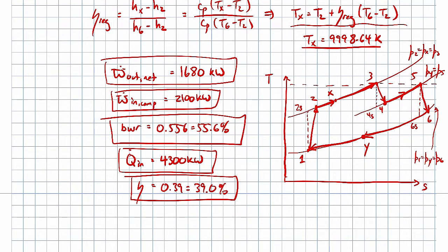That's the lowest pressure. So that's what our cycle looks like when we have the reheat portion for the turbine stages. You can see what happens there is we go along the same isobar, but we increase the temperature. So we're going up like that. And then we have the regenerator, which all that does is shift us further along on the isobar to higher and higher temperatures here. All right, I think that's everything for this example. So we'll go ahead and end it there.